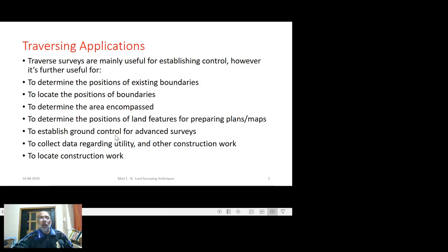But just to get introduced to this, say for example we are dealing with photogrammetry. We are trying to have photographs of a certain piece of land. So in order to link those photographs with the ground network, we can establish a certain ground network initially. The same could be photographed on the photos. Subsequently those photographs will be used to survey or to understand the features in relation to the network that is defined on the piece of ground.